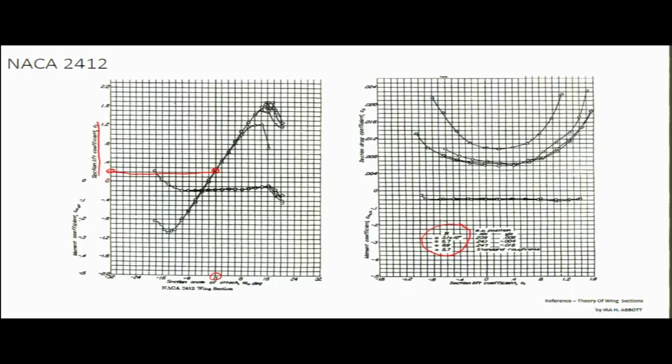This is your 0 CL, and there is an increment to 0.4 here that you can see. Till that increment there are 4 steps, which means each line corresponds to 0.1 CL here. So the corresponding CL naught, which is 2-dimensional, is approximately 0.21.